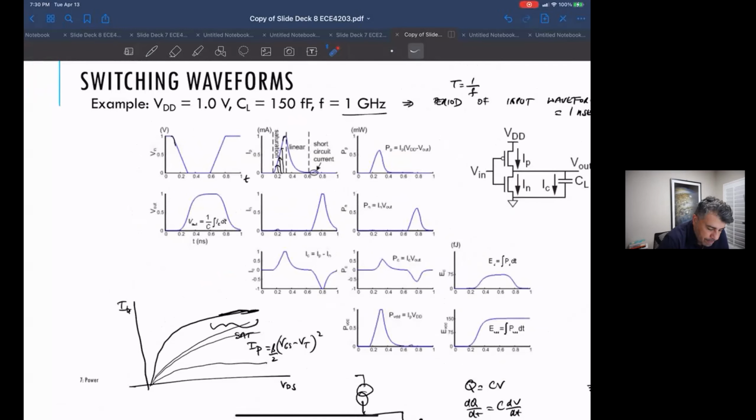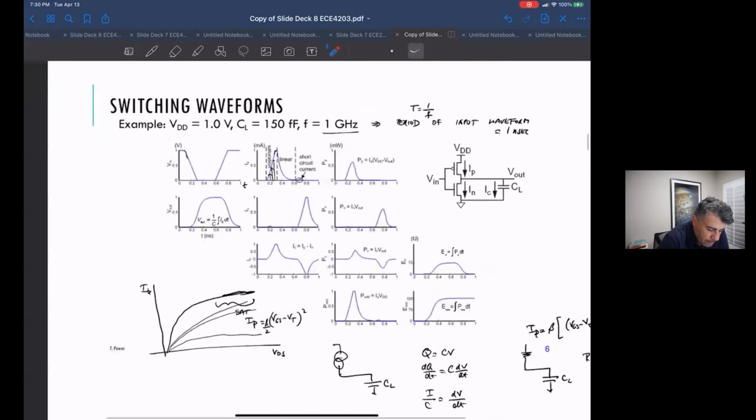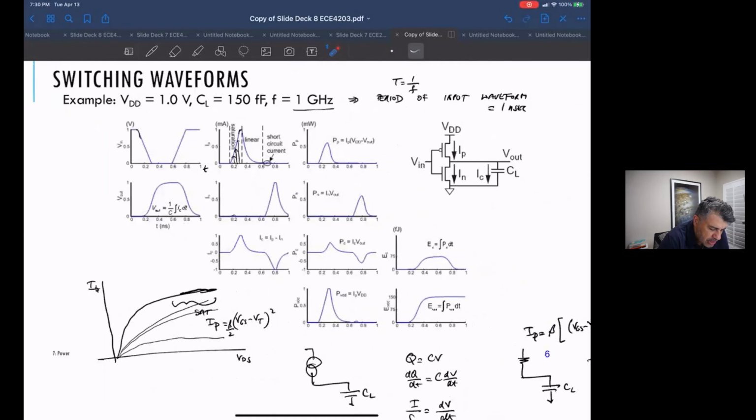No? Okay. So as I go through this in detail, because I think it's hard to get your head around all these operating points that this thing has, but this shows it pretty well. Okay. Now, the next step: we're still on this PMOS curve with respect to time, and what happens is the NMOS starts turning on. So we're not showing the current of the NMOS. This is the next graph here. But at some point, and the PMOS is turning off, let's say we're here.